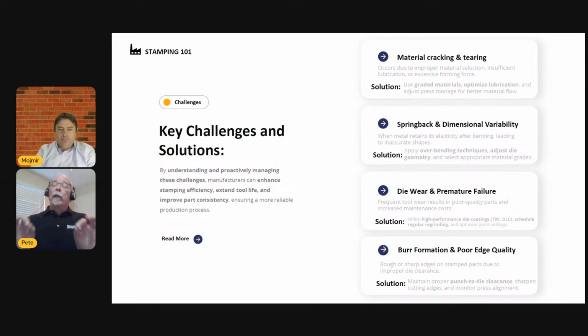Think about cutting clearance. Why do we put cutting clearances in our die? The cutting clearance serves as a lever. The purpose of that clearance is to bend and break the slug out of the strip. We don't want to have zero clearance and extrude a slug out of the strip. We're going to have very high wear rates. So we put clearance in there so we bend that slug and have it break out. So when you look inside a hole, you can see here's where the cut band or the shear band is, and here's the die break area.